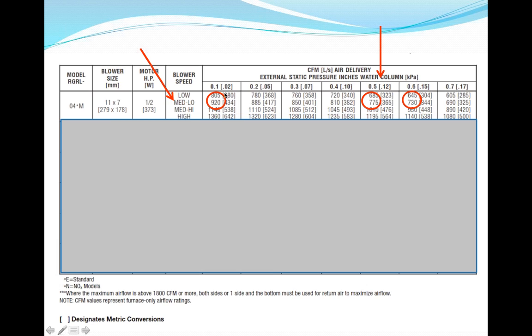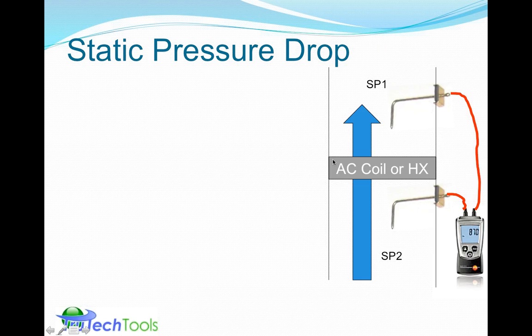It operates at a very low static pressure, very high at the medium-low setting for delivery of air, and at higher static pressure, lower, even like around 25% lower delivery of airflow. So that really underscores how important medium-low has quite a broad definition, from 920 to 730, depending upon the static pressure of the system, which is related to the way the ducts are designed, the way they're installed, the filters that are in place. So that all has a big impact on the system.